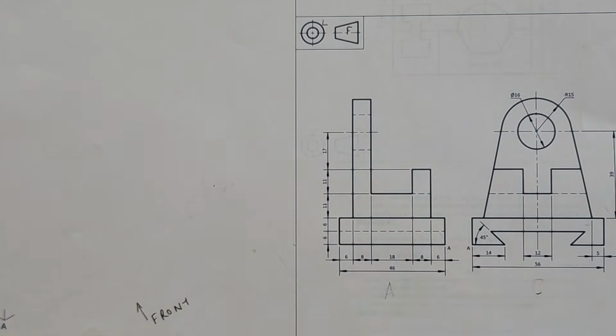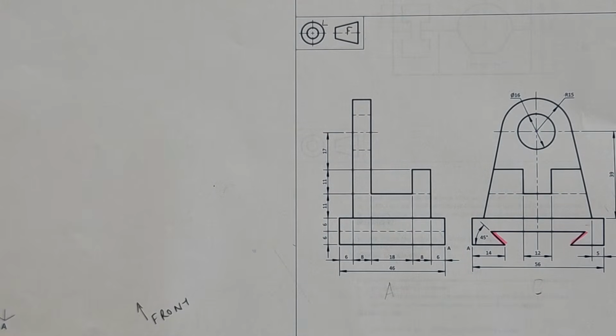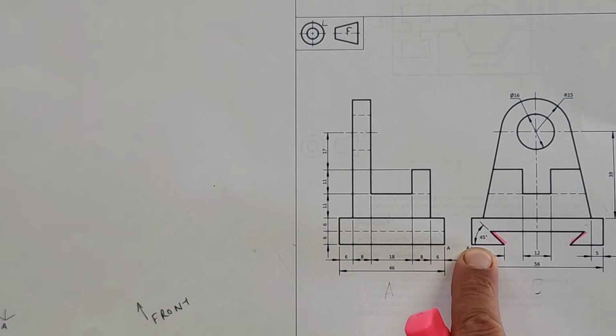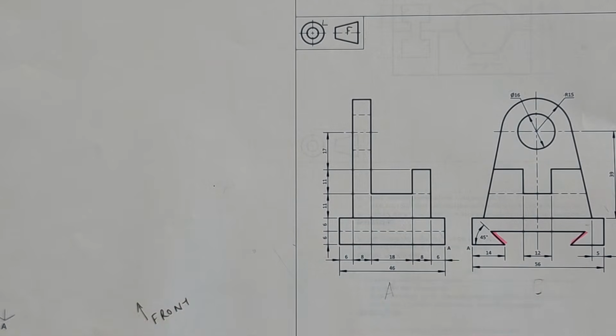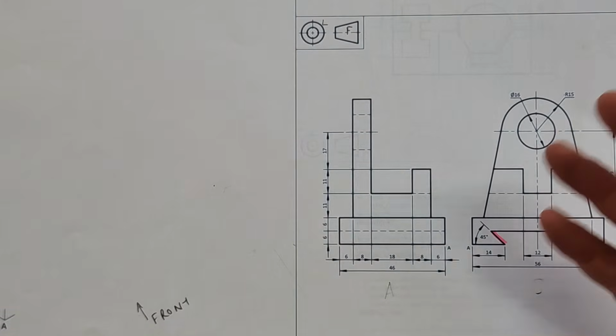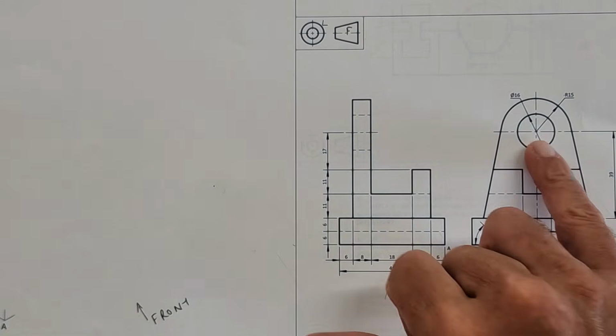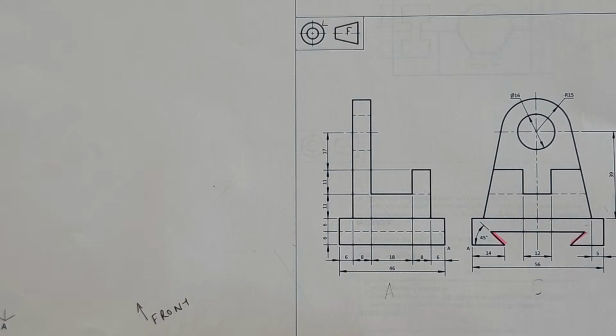If you look at this drawing, quickly look here. Those lines there are called non-isometric lines, 45 degrees. You'll have to draw an auxiliary view for that. What are other examples of lines where you need auxiliary views? What about hexagons, octagons, pentagons? Circles, not an auxiliary view, but there's a different way of constructing them, yes?